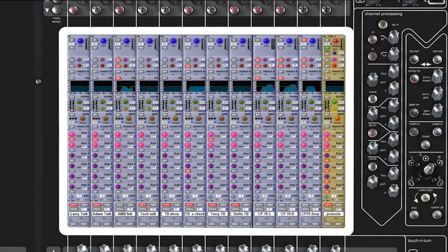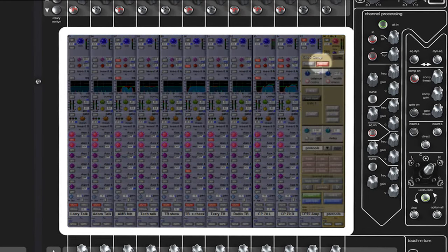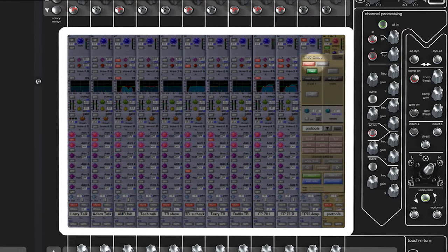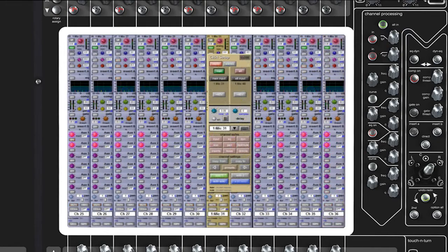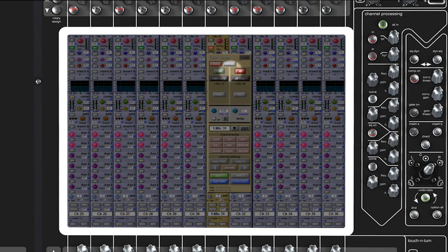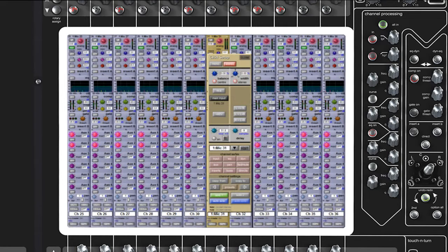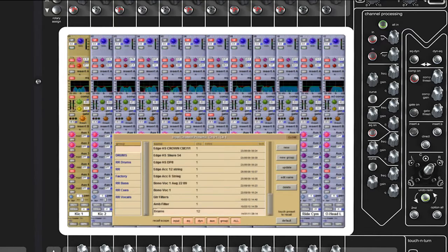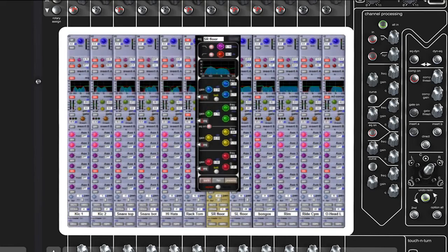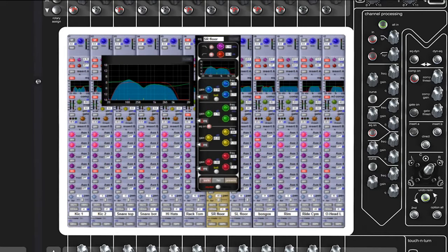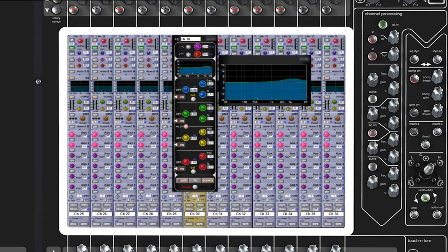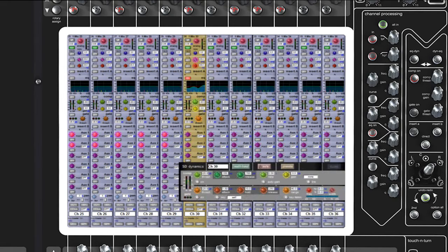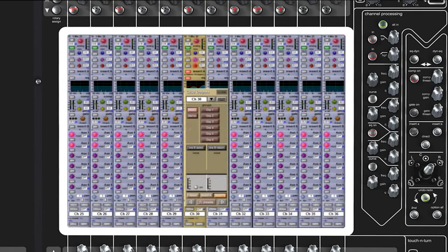The SD10 has 96 channels with full processing, 12 of which can be configured as full flexi channels. All inputs have dual mono inputs for fast main and alt channel switching. Standard input channel processing includes channel delay, single and multi-channel presets, high-pass and low-pass filters with an industry-leading 24 dB per octave, 4 bands of parametric EQ with band curve selection, compressor and gate, dual insert points and access to